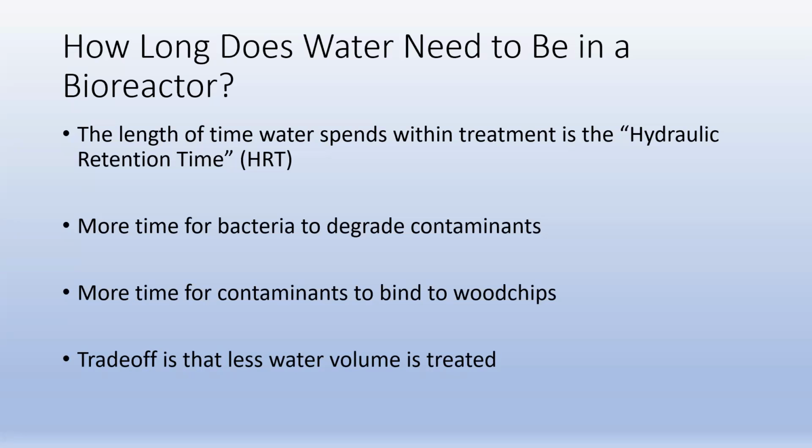There is such a thing as letting water sit in treatment for too long. If you let water sit in these treatments for too long, then the bacteria are going to consume everything in it. They'll consume all the nitrates. Then what are they going to do? They'll move on to sulfur. They'll move down the line, and then you can have some bad things happen if water sits in there too long.